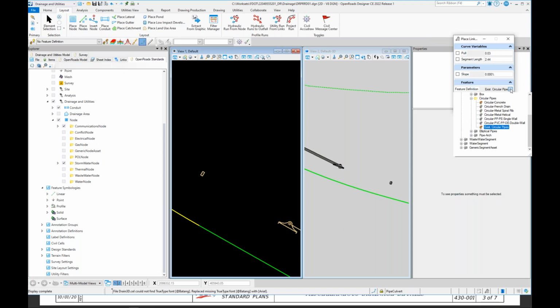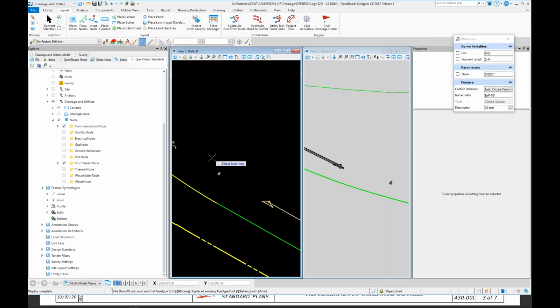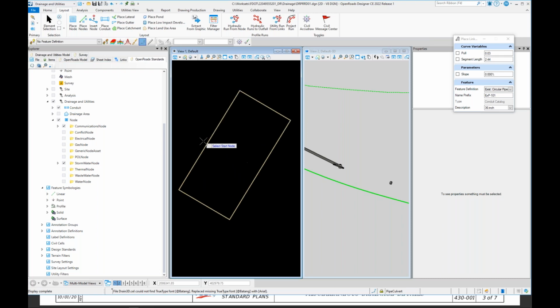Well, since it's already set to existing, I'm going to go ahead and do the existing pipe first. You'd actually be doing the other way around. You'll notice that there are those little tiny dots right above that X. That's going to give you the ability to, no matter where you touch on the structure, on this side, it's going to connect there.